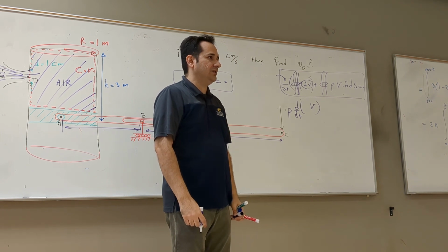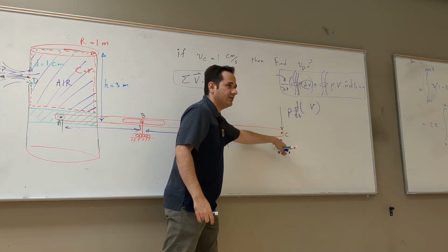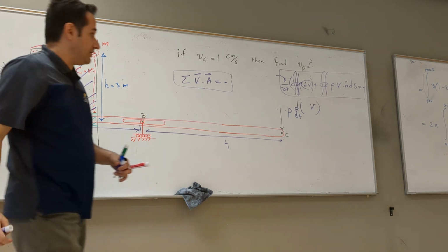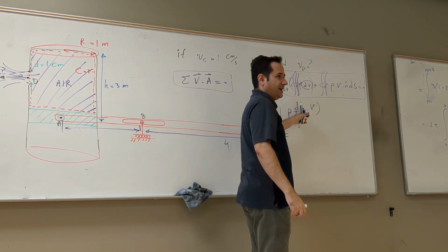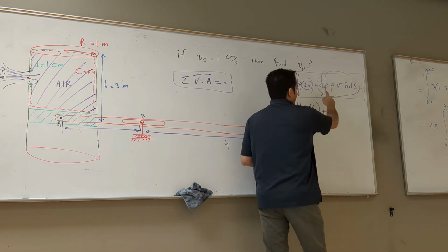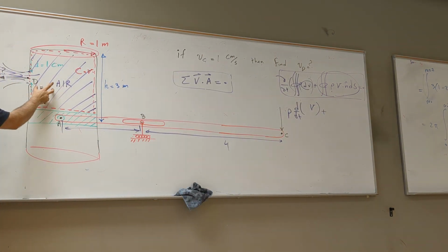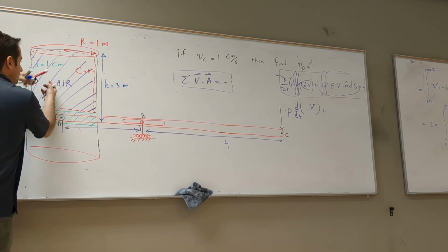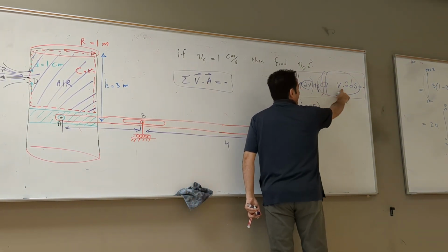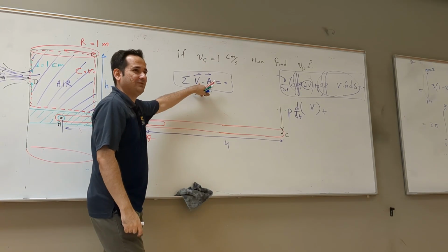No, I can't say that. Because it's just compressing, the moment you apply force here and it goes down, the moment you have kinematic here, there is a kinematic here, and there is a compression here. So you cannot ignore that. So you have to take this into account. So rho times the derivative of volume plus, now this integral. Again, can I take rho out for this problem? Yeah. The density is constant, you see? The reason that we get density constant, because the fluid is not going to compress the air. It's going to exit. So the density is same. So I can take rho out, and then what do I get? Integral v dot n dS. What was that? I ended up with that.